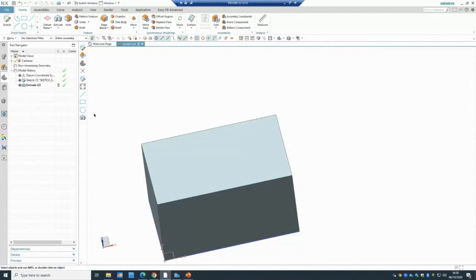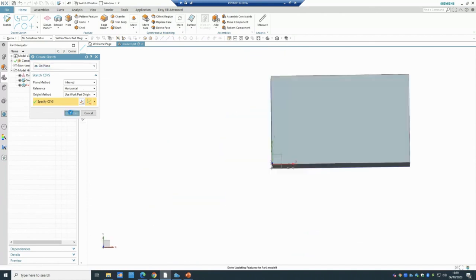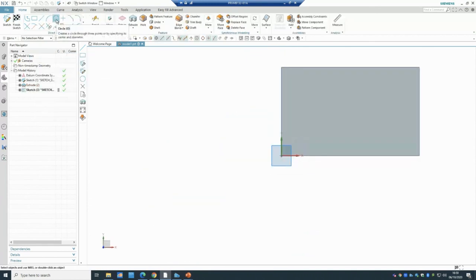Okay, if you want to do a cut, you have to first have a sketch, and the sketch needs to have the plane first. So you go to the sketch, and the software asks you to choose a plane. Rather than choosing the plane, I'm gonna use the faces that I have here. Let's say this face, and I use invert. Technically, just use that face as a plane. We'll talk about the planes later, but it's okay.